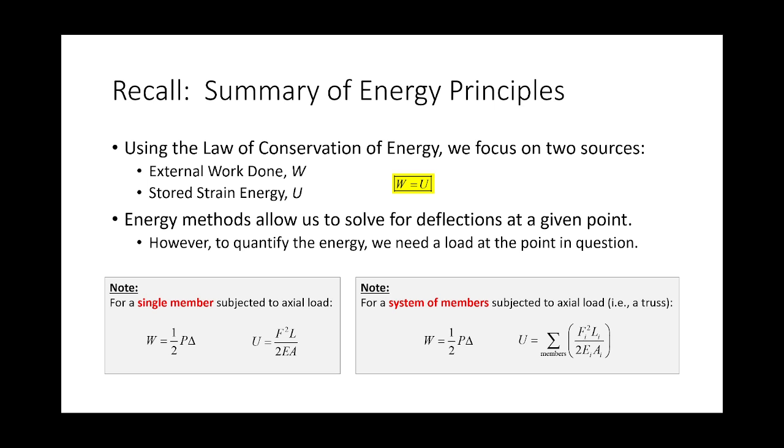And one of the reasons that deflection limit is present is because if your roof beams, or your beams that are supporting your ceiling, exceed L over 360, the idea is that if you have a plastered roof, the plaster will start cracking. It has nothing to do with whether or not the structure is going to fall down and kill somebody, but obviously we wouldn't want the plaster to crack in our roofs, right?